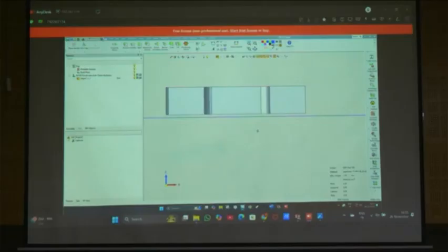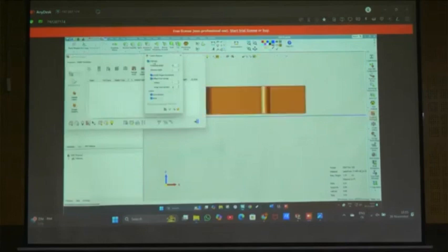We can apply the support, but here I kept a body of 1 mm. The recommended value is 0.3 mm to go for the wire cut EDM. 0.3 mm is enough. Just to apply some different supports I kept it. So support manager I will keep. See, these are the parameters. 30 is there, I can keep it as 45.